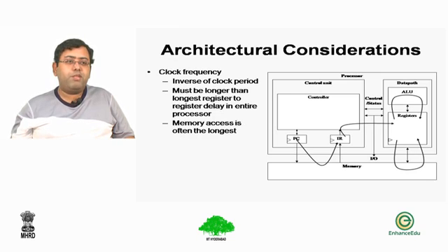One of the important aspects of choosing the processor is the clock frequency. The clock frequency must be sufficiently high to produce the results within a reasonable time frame, and it should be sufficiently low to ensure that not a lot of power is being dissipated. So it is again an optimization problem to solve. What should be the right clock frequency for the particular application being concerned?